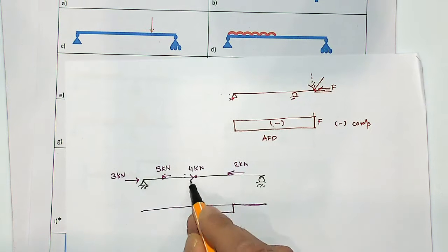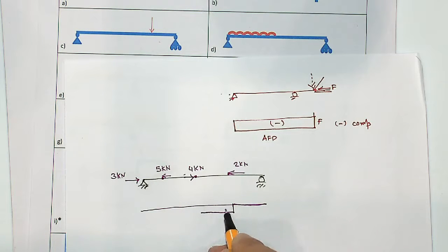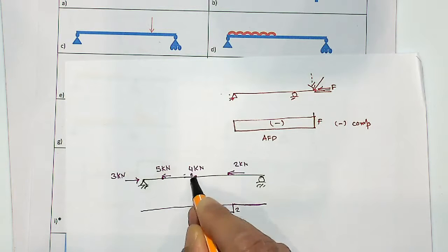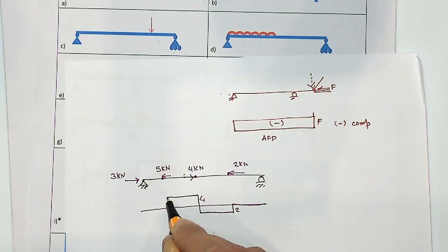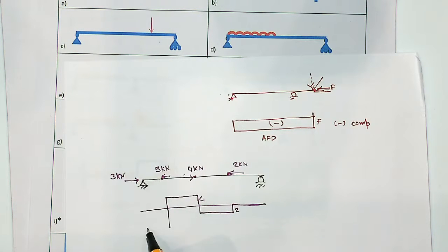So this is 4, and then that is going to create a tension. So this is 2 minus 2, and then that would be 4, because that's in the opposite direction, and then that is 5 coming down into 3 units there, and then again here is 3. So that is the axial force diagram for this case. So you just add and subtract as it is.